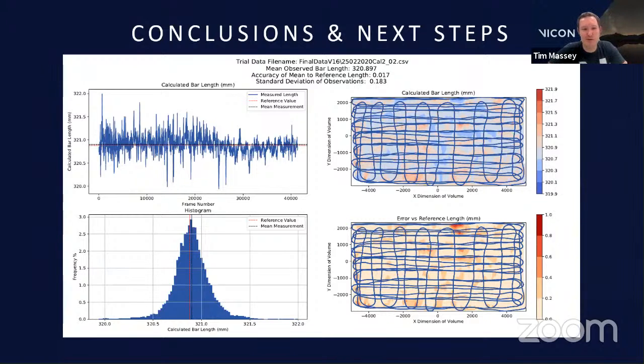You don't have too many temperature fluctuations, which can affect not just the cameras, but the mounting, through thermal expansion. There's a very interesting example of that outdoors where the sunshine would shine onto a camera mount, which was a long pole. One side would expand, and that would warp the mount slightly, and that would affect the data quality.